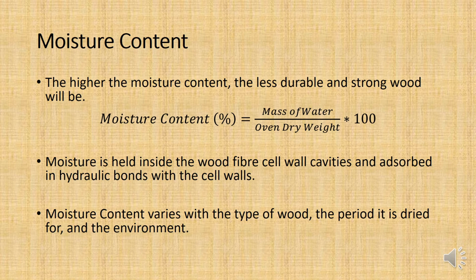Generally, there's more moisture content in evergreen or softwoods than there is in deciduous trees or hardwoods. That's a generalization. But what is not a generalization is that the moisture content, or the height of moisture content that can be raised to, is higher in sapwood, that outer ring of the lumber, than heartwood, the inner rings.